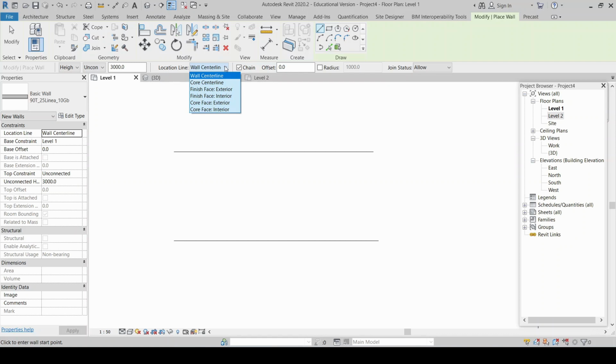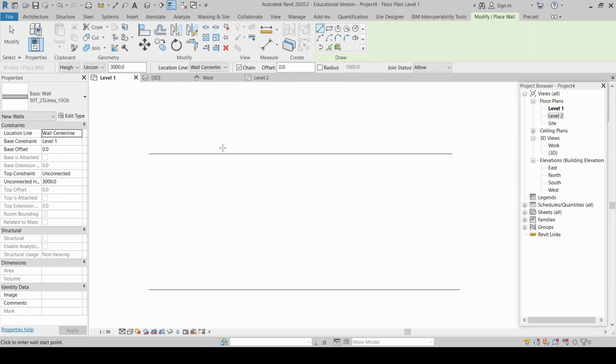So when Revit builds walls out of various materials and builds them up to be realistic to the actual physical construction of the wall, it uses something called a core. It divides the wall into 3 parts. It has a finish on the exterior, a finish on the interior, and the core. The core is the middle section of the wall. So on a timber frame wall, that would be our timber framing. The finished exterior would be the linea or the weatherboards, and the gib on the inside would be the finished interior. So I'm just going to draw a wall, and hopefully that will explain clearer what I'm talking about.